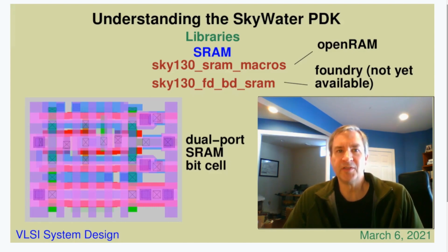The original sources from the foundry included only the core SRAM cell layout, and so the OpenRAM project is creating the additional cells needed for the decoding and driver circuitry. Eventually, these cells will be put together in a library and either added to the SkyWater PDK or maybe just left as a third-party library.